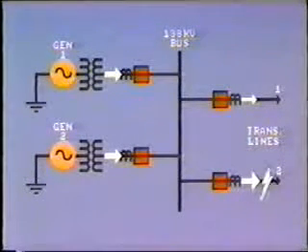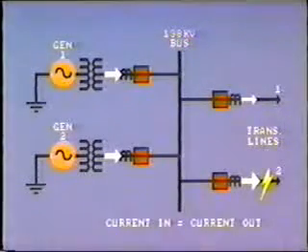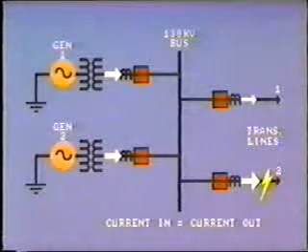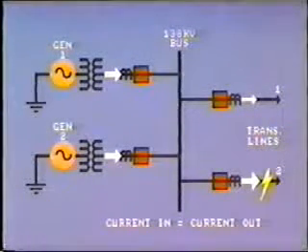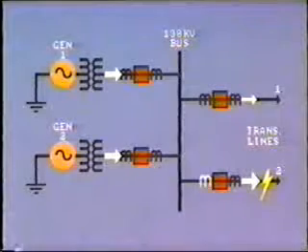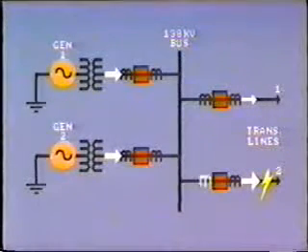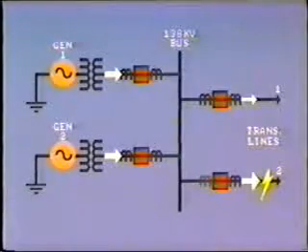Even if there is a fault on one of the transmission lines downstream, the sum of the currents is still 0, as the total current entering the bus is matched by that leaving. The downstream fault would be cleared by other protection relays activated by the inboard CT here.